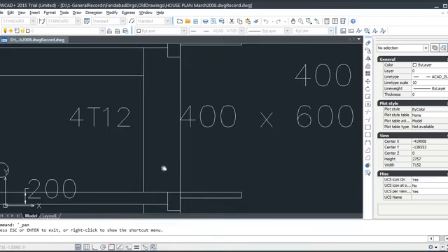So it's better we go down, start from here, go up, let us say 40 centimeters we cast, and we fill that 40 centimeters and provide a vibrator here, then take out the vibrator and bring it again maybe after half an hour, after pouring the same 40 centimeters or 400 mm in all columns, however many you have. Then another 400 like that, applying the vibrator, and this vibrator nozzle must go down into the previous layer also for the purpose of interlocking both layers. And like that it moves until you reach 4 meters here. That's called one stage pouring, which is professional pouring.